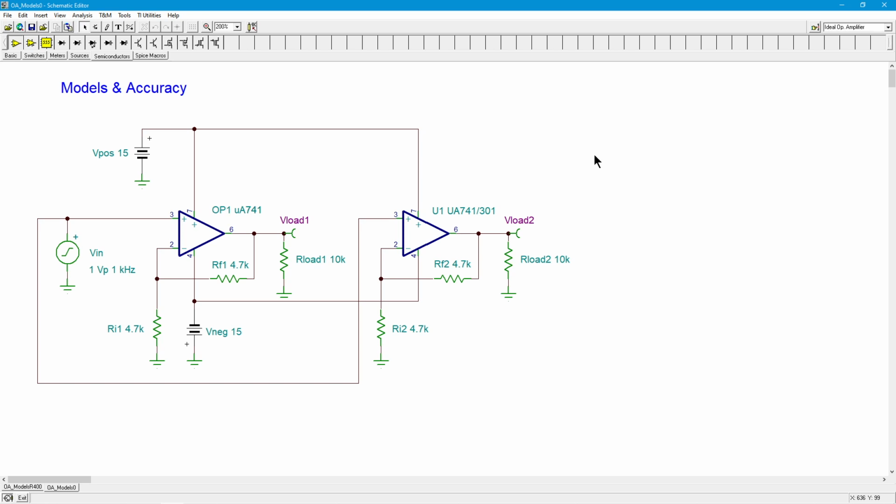And then what we do is abstract that one more level. We come up with a model of that physical realization of the concept. Okay, it's not a philosophy class, but bear with me. So the question is, when I compare this one to this one, is there a practical difference in terms of my simulation results? I can say, well, there's going to be a computational difference, and maybe it's negligible if I'm just doing a single stage, 2-stage, 3-stage amplifier, but in a much larger schematic, maybe it's going to be a performance hit. I'm going to have to hang around for a few more moments to get my results.